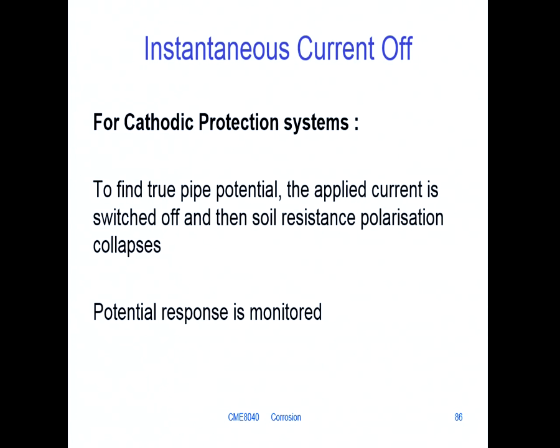Can I ask regarding your explanation about stress corrosion cracking? As I understand from your explanation, because of the passive film, the surface all passivates, but if a stress causes that film to crack, you'll get corrosion, and then it'll passivate again. Because the film is brittle, every time there's a bit of load applied to it, it cracks. Then you get corrosion, then it passivates. So it's a stepwise process.